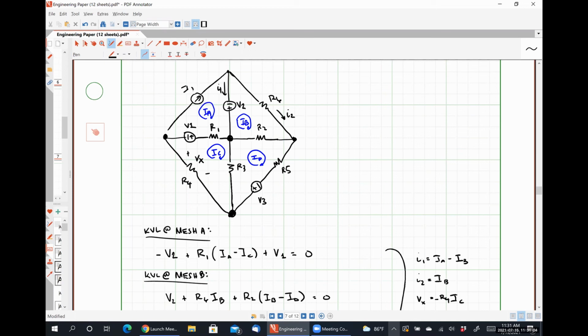you would have some current source IX here, which would eliminate one of your equations. Right? There's still 4 meshes, but you know that IA is exactly equal to IX, which means you really only have 3 unknown quantities. Something like that, absolutely, I will be a jerk and do it. Or I might give you a question where it would require the use of source transformation to make it into a 3 equation, 3 unknown system or something like that. But something where the only way to solve it is 4 equations and 4 unknowns, not a chance.